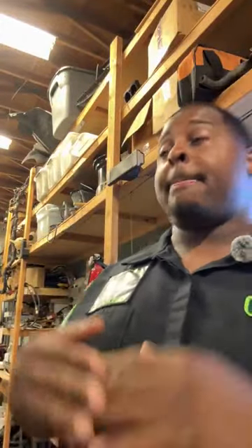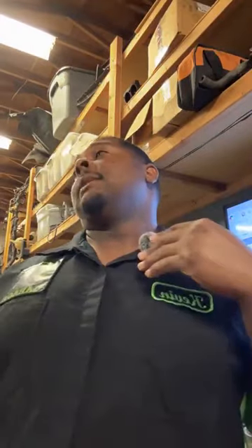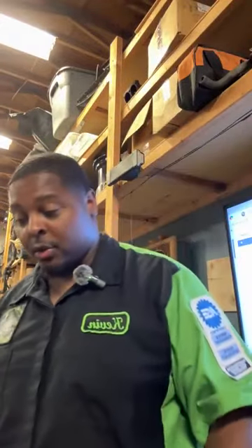And I always recommend, don't shoot me in the comments, changing the whole fuel pump assembly. The whole thing, the sending unit, the pump, everything. You can save $1 or $2 by buying just the pump. However, that fuel sender assembly has been in that tank as long as that pump has. It has been exposed to raw fuel as long as that pump has. And the pump has failed or is about to fail. Why not change the whole assembly and make everything fresh and brand new? Especially if you don't want to have problems with fuel gauge reading down the road.